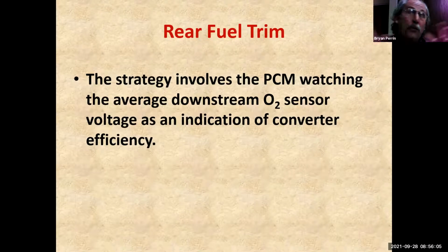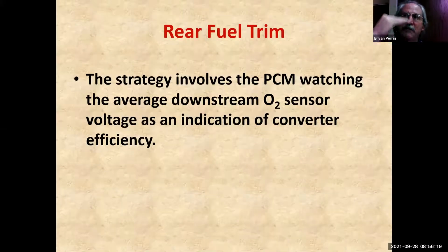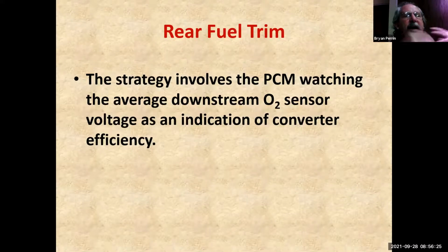So you see, they both control mixture. They both control lambda. They're both going to affect what comes out the tailpipe. But one is switching quickly so the cat can binge and purge the oxygen out of the cerium. The other is managing what's coming out the tailpipe by controlling the ratio. So it's really fascinating how all these pieces go together.